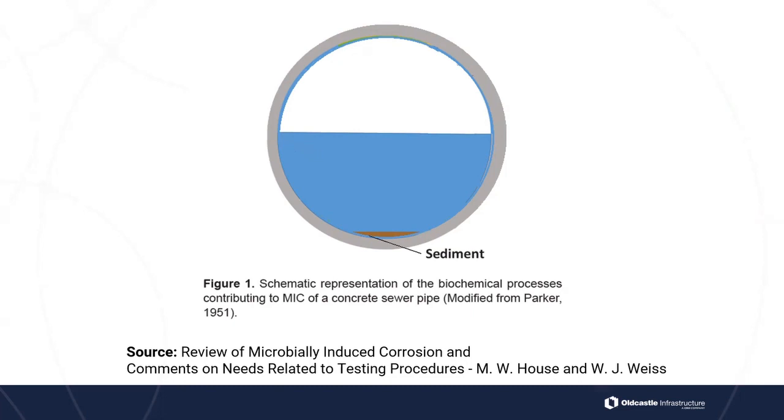Okay, the release of H2S gas or hydrogen sulfide gas depends on a few things. Number one, the turbulence of the water is the main contributing factor. For instance, just upstream of a pump station, we see this very common and happening a lot just upstream of pump stations. But it's also dependent on higher waste strength of the water, lower oxygen level in the water, just to name a few.